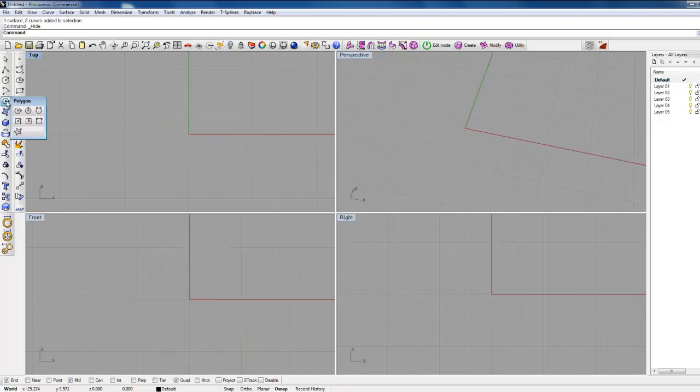And if we click on this polygon shape, there's a star one there, we're going to use that. Centre of the star, again we want this in the world origin, so we'll click 0, press enter. So we've got a star coming up there. Or we've not got pentagon, haven't we? So what we'll do is set that, set wherever you want, and then pull that in. What we've got then is a star shape.